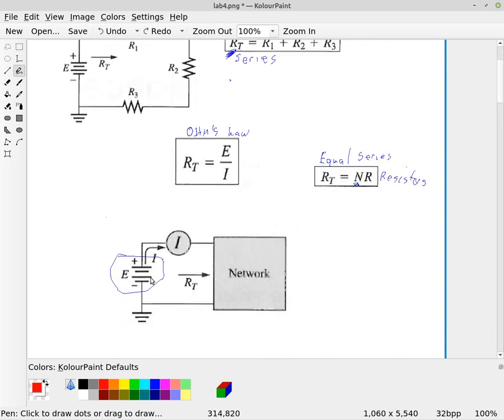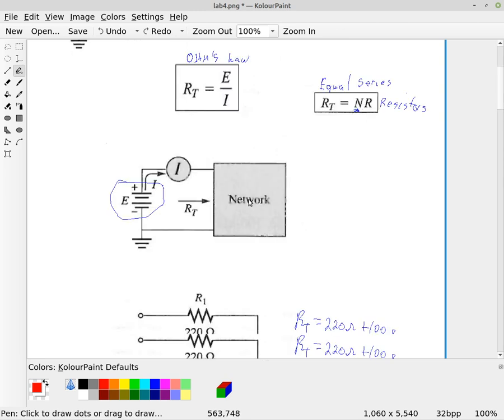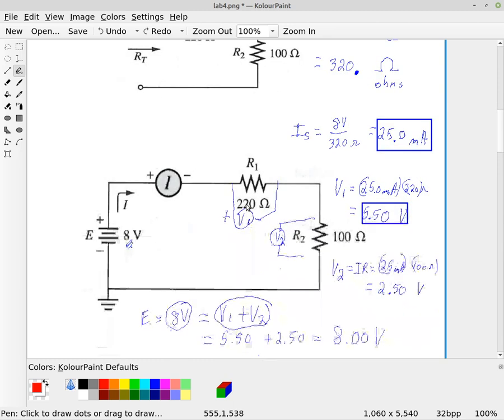You just have to apply it appropriately. So when we're talking about a series resistive network here, we first find our total, and then we can use the total supply voltage to find the total current into that series branch. Okay. But then down here we also found that we could, after we know the resistance and we already found the current, we could use Ohm's law again to find the voltage across just this one element.